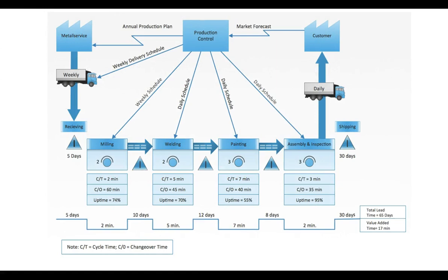Again, this is integral to a value stream map using Little's law, and the main reason is that, like we went over with value stream maps in module 1, they not only show the flow of the product going through your process, but also give you the key metrics that go along with it. So you can see exactly how much time is being utilized at each particular part of the operation, as well as how often they're shipping and how often you've got them coming in. You can put a lot of numbers to it.